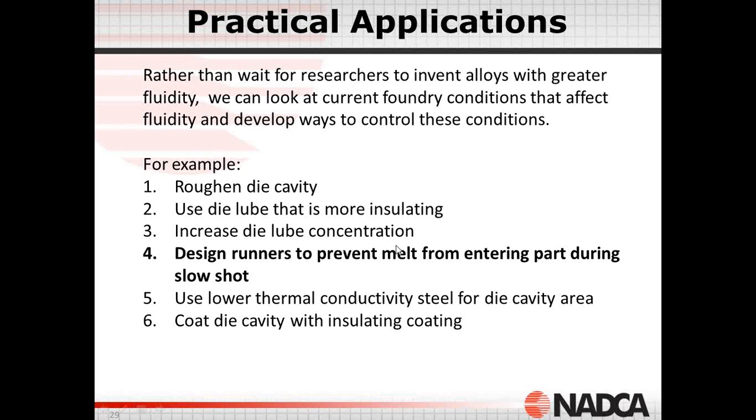So a richer die lube will, of course, be more insulating because it deposits a thicker thermal barrier onto the surface. And of course, as we've seen, designing runners to prevent the melt from entering the part during slow shot is critical in making these castings.